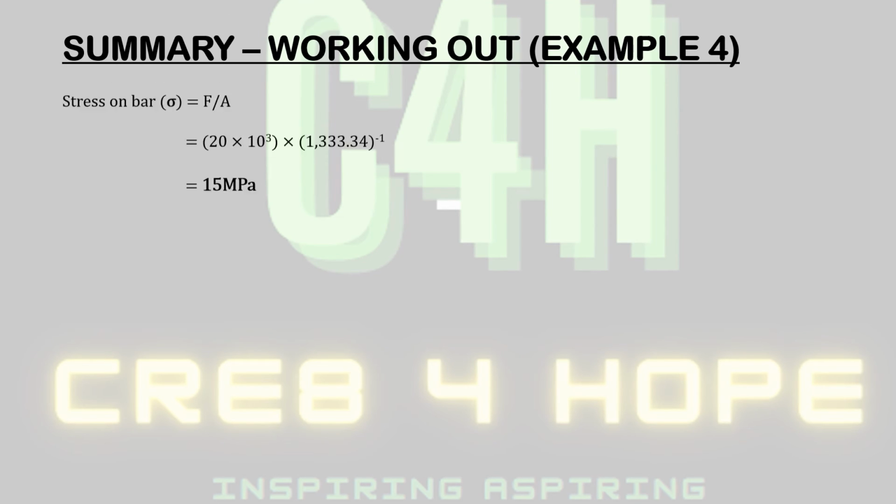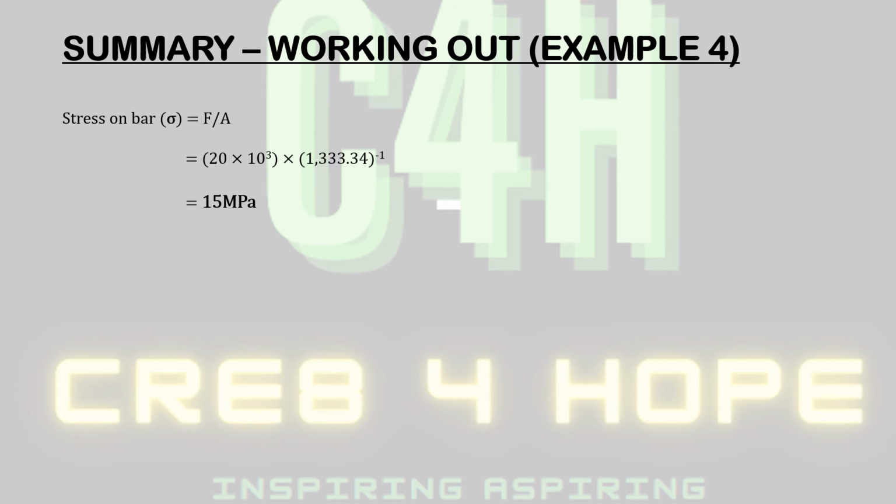So now that we have all the variables that we need to calculate the stress, since stress is equal to F over A, and don't forget that F is the deforming load, which is 20,000, divided by the area, which was worked out to be 1333.333, that would give us approximately 15 MPa. So now that we've worked out the stress and we know what the Young's modulus is, we've got all that we need to calculate the strain. So strain, epsilon, is equal to the stress divided by the Young's modulus.